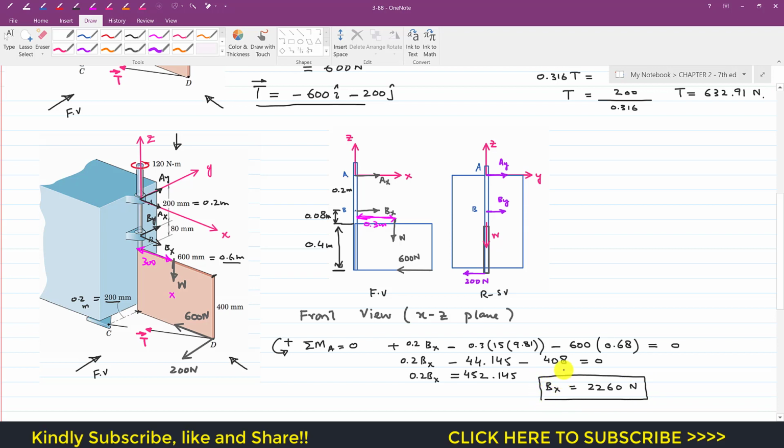Now we have to find By. Again we have to consider the right side view. Let me write that I am going to consider the right side view, or we can say that we are considering the YZ plane. So this is our YZ plane, and now as we can see, again we have to find the summation of moment about point A. That must be equal to 0 since the system is in equilibrium, and the counterclockwise moment is positive. Now as we can see, this By is producing the counterclockwise moment, so I will write plus By,